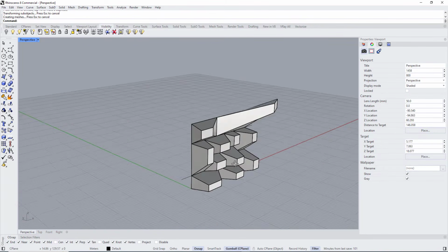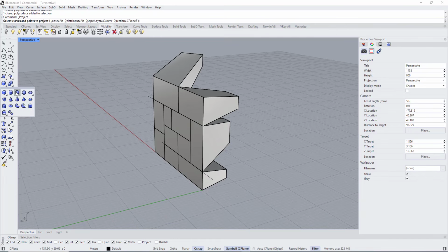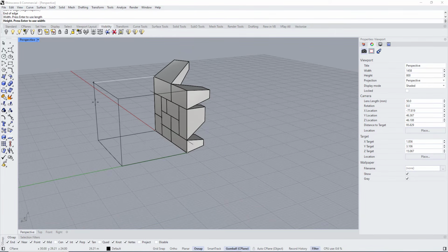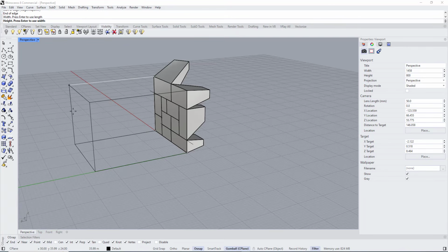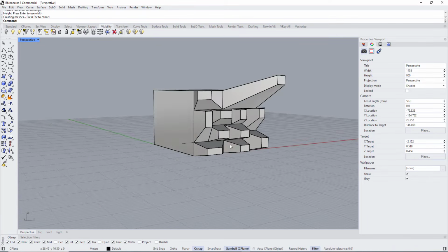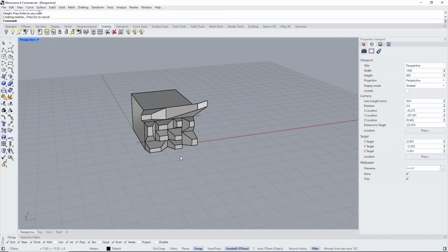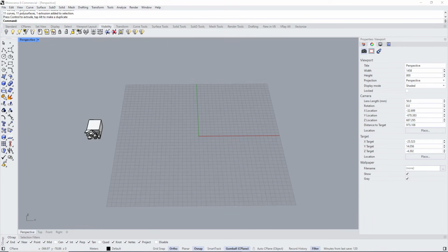So after finishing adjusting the shapes, we can model the back of the building. It's just a box. I come here, I choose box and choose 3 point, first point, second point, and maybe 35 meter. Oh, okay, sorry. Again, 3 point, 1, 2, 3, and type 35. Okay, negative 35. And here we go. Okay, let's move this away and start modeling something else.